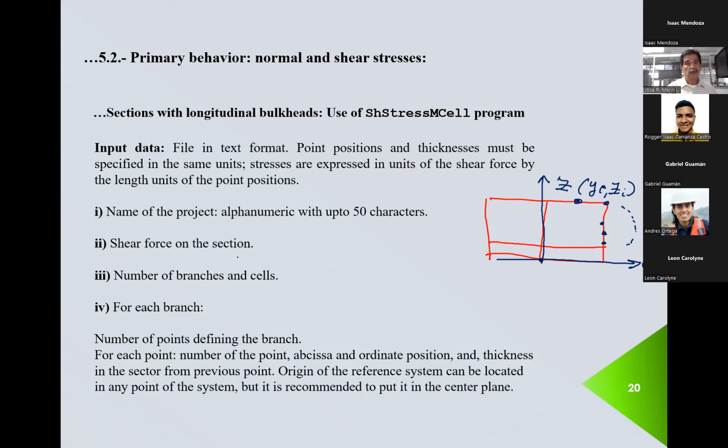Then the shear force applied on the section, okay? If you have the shear force, well, you can use it here. If you do not know, my suggestion is that you can use 1 newton, right? That means that since this is a linear problem, if you have a different value, V units of force, the result is going to be simply the number V of shear force multiplied by any of the results that we are obtaining, because this is for unit shear force, okay?